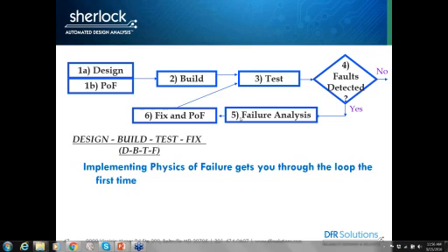Tin whiskers. We have a question: discussion on tin whisker defects with Sherlock modeling. Tin whiskers could be considered a defect, as you say. If the plating is done too fast and you build up a lot of residual stresses, you can form whiskers very quickly. The one thing you could do, and we haven't implemented it yet in Sherlock, is look at lead spacing.